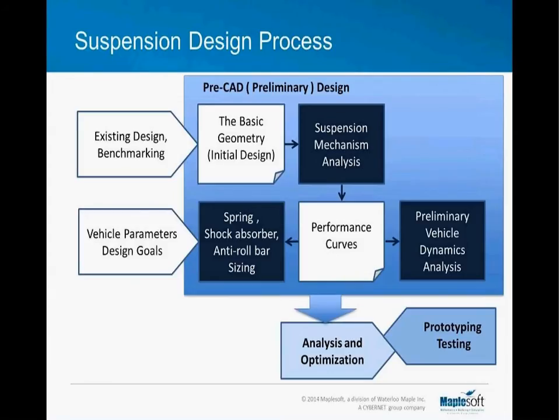So now let's take a look at the suspension design process specifically. Again, as you can see from the benchmarking phase, we have some data about the existing design, about the vehicle parameters, about the design goals, and based on these inputs, we can have a basic geometry of the suspension system. It's not the exact geometry. We know the mounting points, the hard points, but they are not finalized. It's very rough